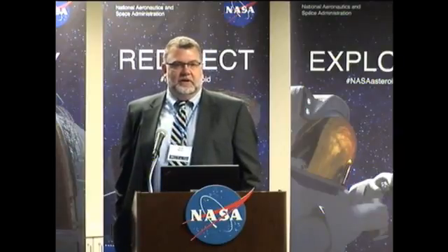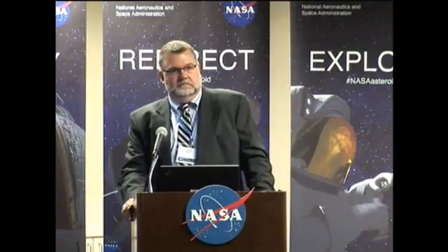And that was looking at the worst spinner, the highest mass for that worst spinner, collapsing in, and then taking that torque, applying it at the base of the booms to the spacecraft, and seeing if we busted or not. With these flexible structures, I mean, it really requires a fairly detailed 6DOF analysis.